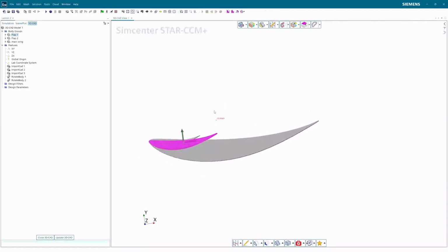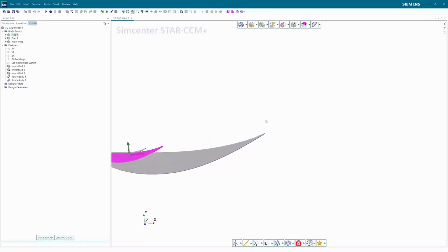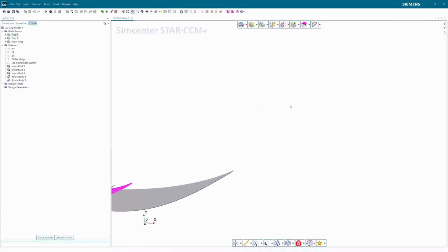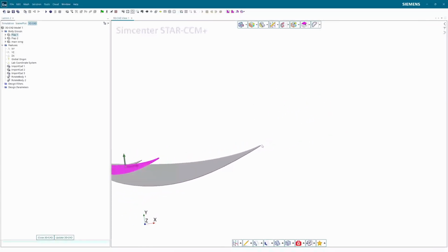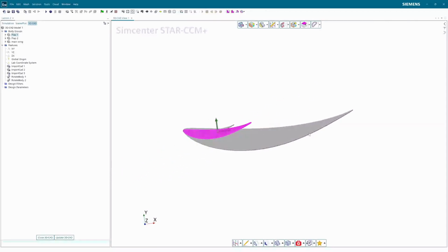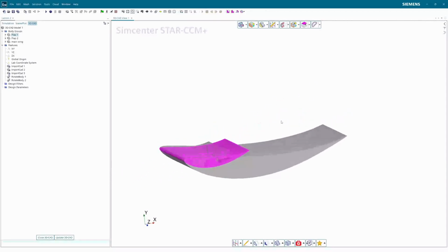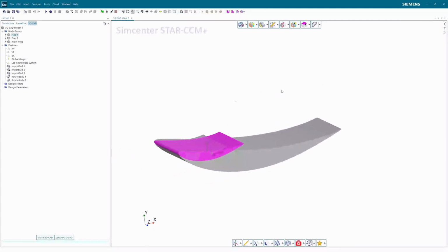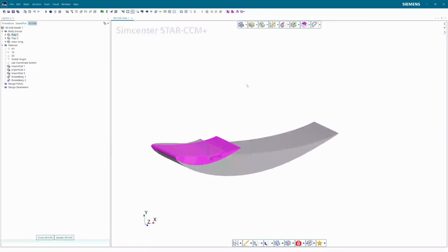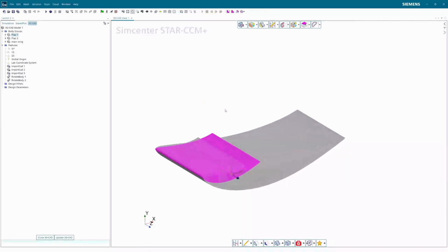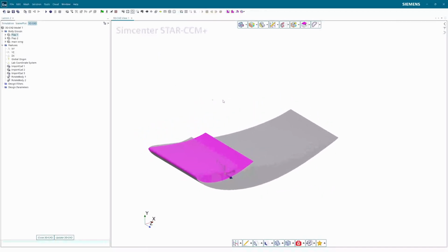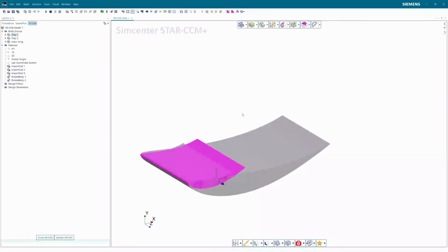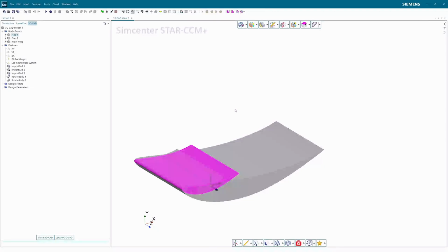So what we're going to try to do is to have these wings appear right behind each other in a way where if I have a certain setting for the first flap and the second flap, but I change, for example, my angle of attack for the main wing, the other parts will follow suit. First things first, we'll be doing a couple of transformations here, and the order of these transformations is important. If you do them in the wrong order, then your results will vary.